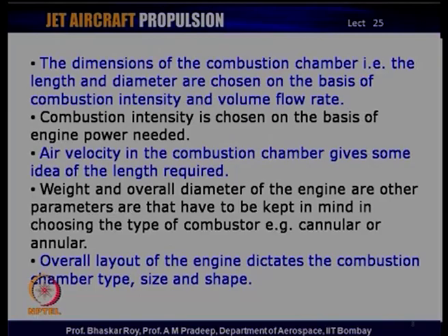So, the power or the thrust power that the engine has to produce can be a deciding factor on what the combustion intensity is going to be. The air velocity in the combustion chamber, as it is coming from the compressor, gives a certain idea about the length that is required. And we have talked about the combustion mechanism, probably we will have a look at it all over again a little later today.